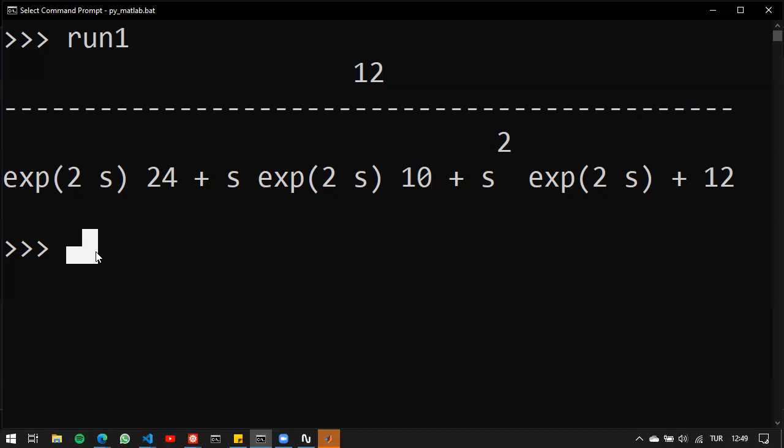Or in this lesson, we will see how to use the Padé approximation to overcome the problem. And let's do the Padé approximation. The Padé approximation tries to come up with a valid transfer function that we can use, that we've learned to use up to this point. We were using the characteristic polynomial and all sorts of stuff to design controllers. What if we can somehow approximate the e to the power of minus 2s term and then get a valid characteristic polynomial, and then just design our controller as usual and apply that controller to this system?